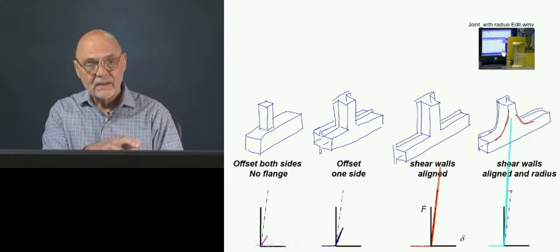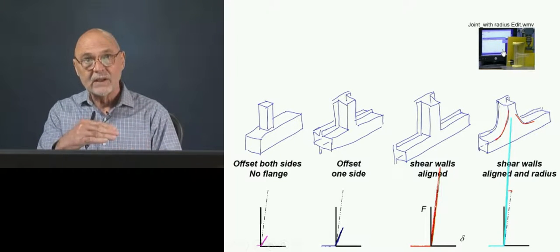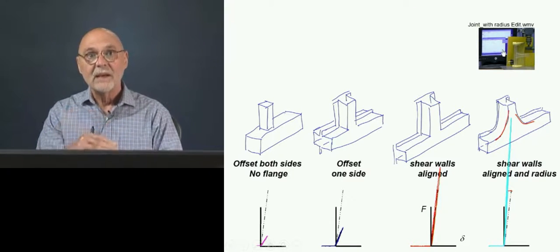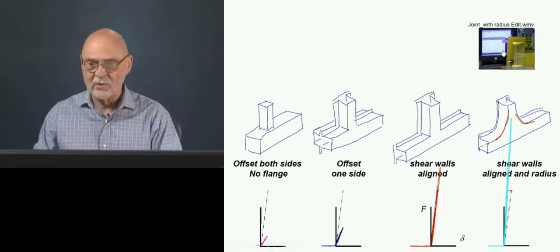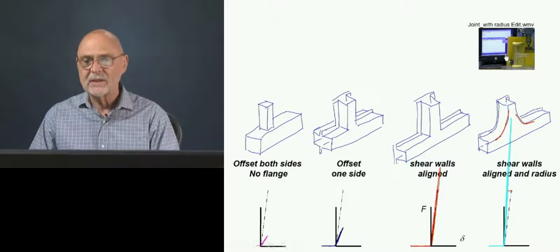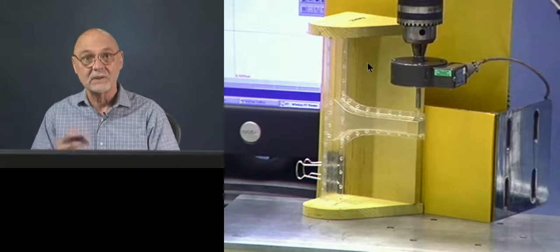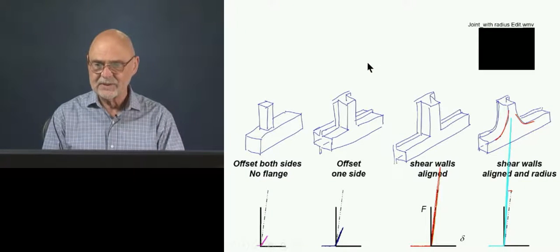And if you remember the first one that I showed, basically when we were pushing on the B-pillar beam, the little horizontal beam, it looked like it was perfectly rigid. It wasn't flexing at all because the joint rigidity was so low. Take a look at this one and you'll see that this bar is actually bending like a beam. I think you can see that. It's sagging like a little cantilever beam. So you see the joint has very little deformation. Most of it is in the two beams here. Okay, that's the desired end state.